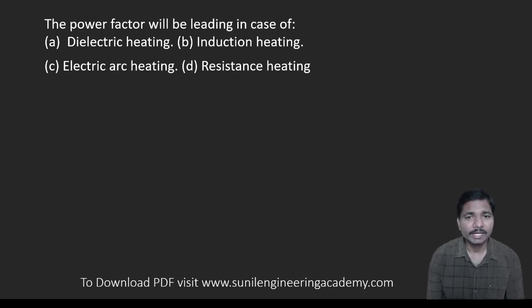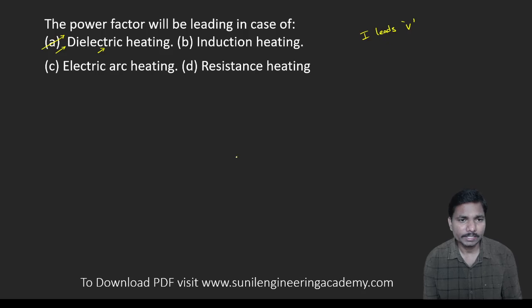The power factor will be leading in case of which heating? The power factor may be leading in case of dielectric heating. Only in dielectric heating is there a chance of leading power factor. Why? Because the current leads the voltage. So the answer is option A.